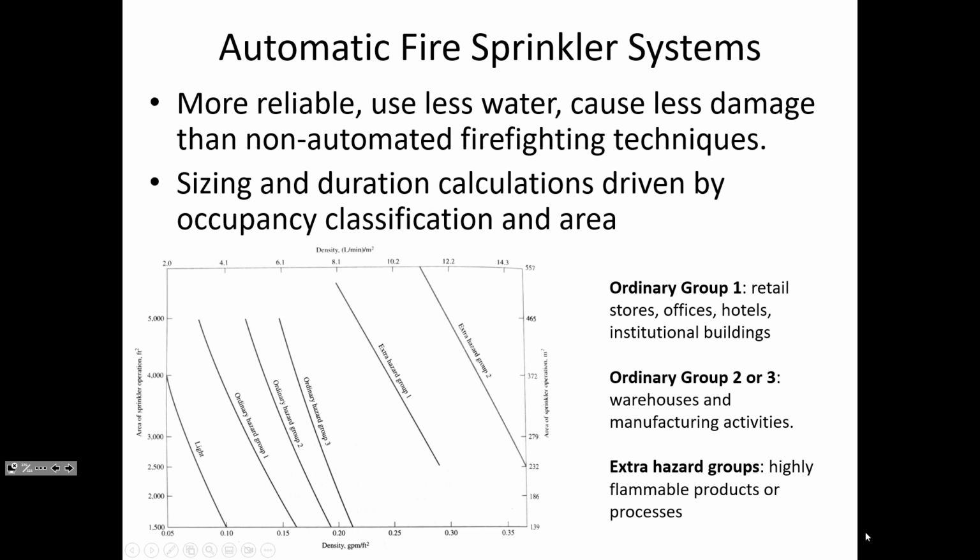So they're great. But we need to make sure to provide into the building and into the pipelines that are providing water to the building enough water so that there isn't a huge pressure drop in case of a fire incident. One of the figures that our book illustrates is different classifications of hazard risk. Obviously if you have, for example, a warehouse that's holding flammable materials, then the amount of water that would be needed in case of a fire is much higher than for an ordinary industrial building or residential structures, where there's going to be a lot less quantity of flammable or potentially explosive things.